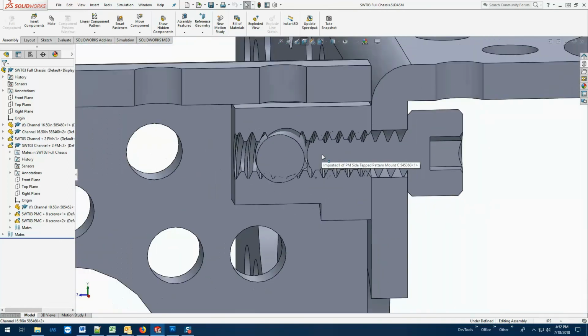And you can see that my screw head for the 0.25 screw is really starting to intrude on the threads of the 375 screw. And you may take that knowledge and say, this screw does not fit there, I need to use one of the other threaded holes on the mount instead of using the 0.25 screws here.